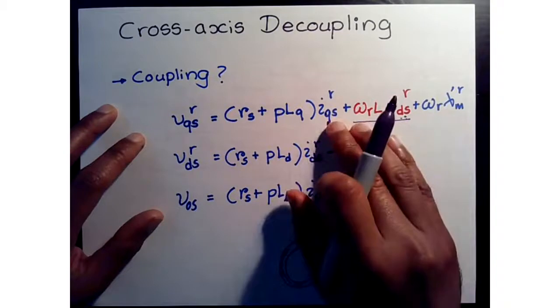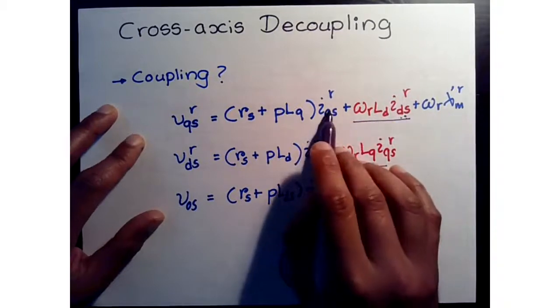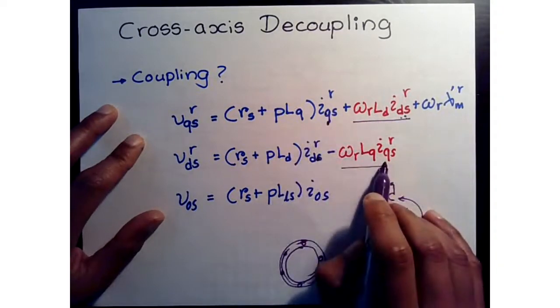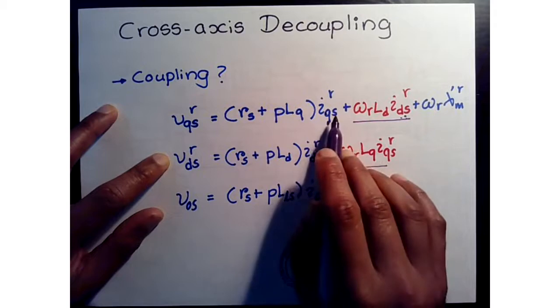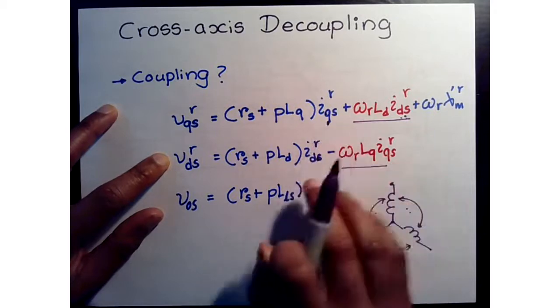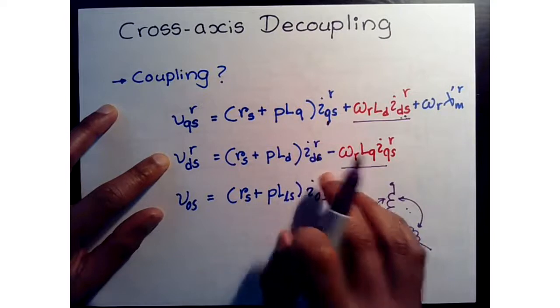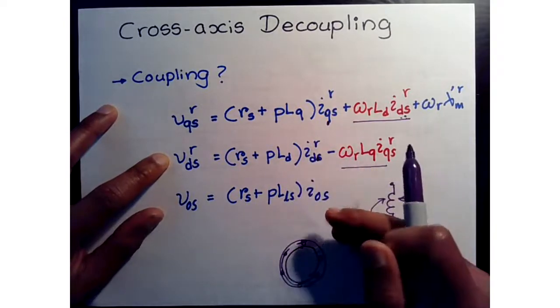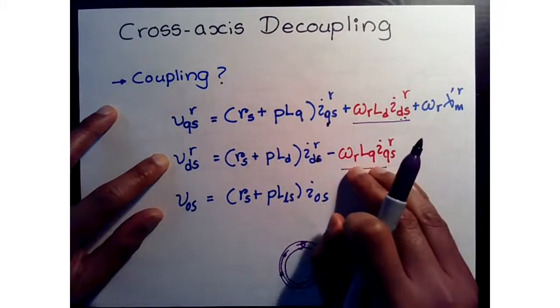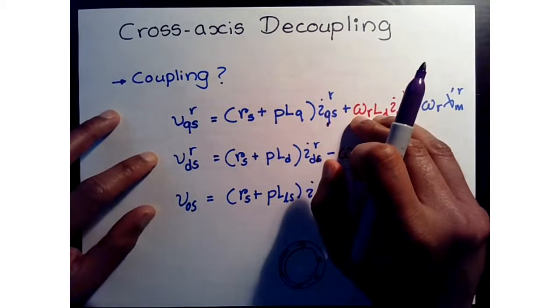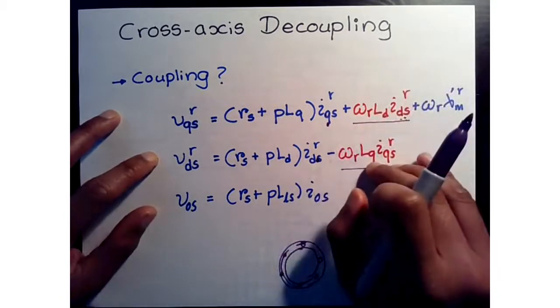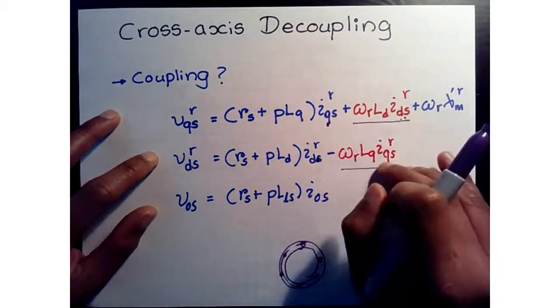When we do that, that reference will influence what? It's going to influence my d-axis. So that means a change that's only occurring or that was requested on the q-axis is going to make the d-axis work, and then the regulators will have to work and try to regulate the d-axis voltage as well as the q-axis voltage. So this is a little bit undesirable.